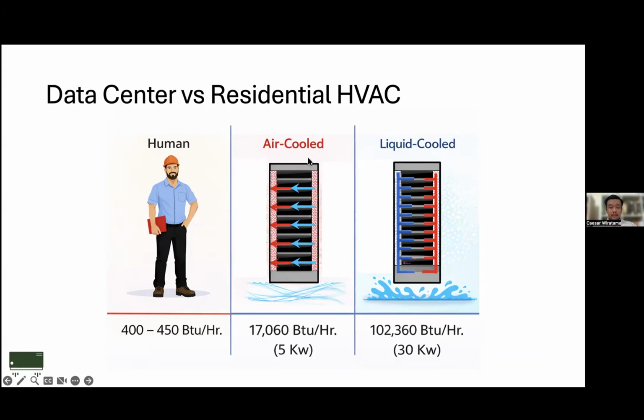And here the air cooled has much less energy density compared to liquid cooled, because liquid has about 10 times the density of air, and the heat capacity of liquid is much larger than air, so it dissipates energy better.